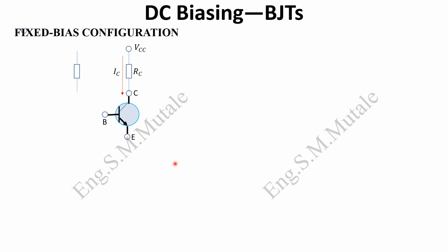Then we are going to connect another resistor on the base. These circles are just points of connection, and you give it excitation as well, VCC. We call this resistor RB, or the base resistor. There's a current passing through there which we are calling IB, the current passing through the base, and we are exciting this with the excitation voltage VCC. We excite both the base as well as the collector like that.